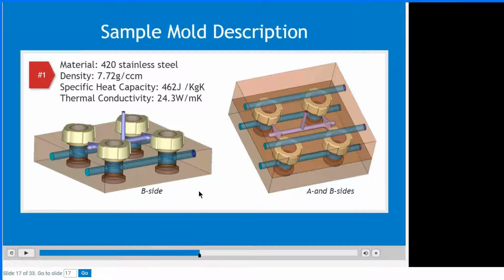Again, simple training for mold steel. What we have here again is two water lines on A and B side, and a water jacket around an insert that forms the inside of this inner core. Okay, that's our starting point when we evaluate mold steel selections for this particular part. Again, right now everything is out of 420. Okay, let's see what happens.